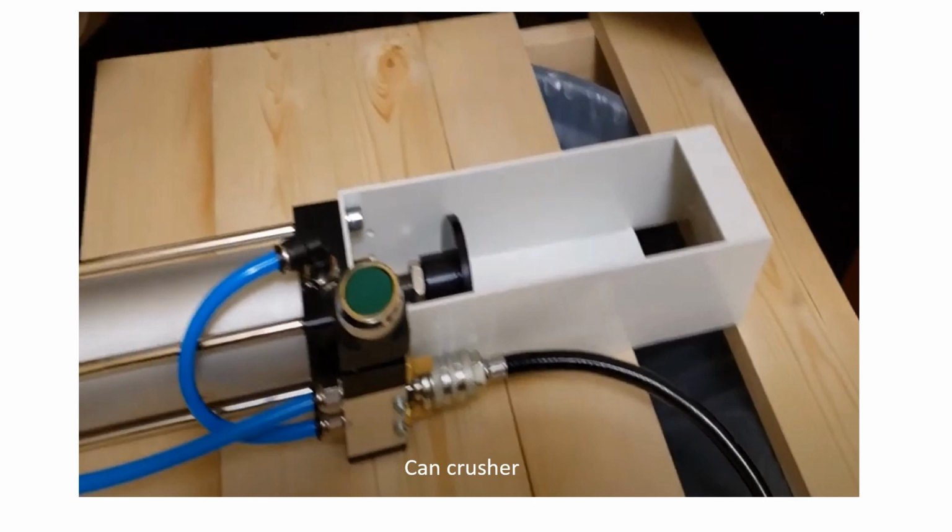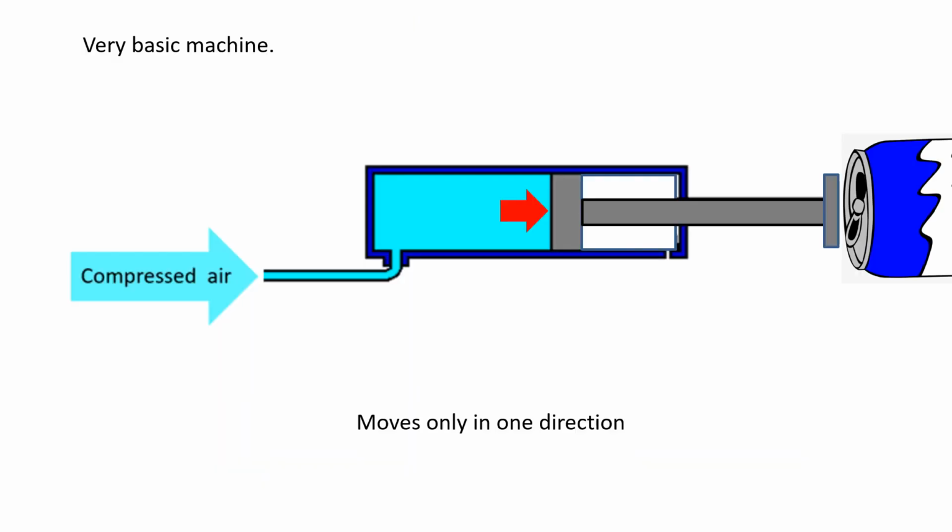Note the operation: as the operator removes his or her finger from the actuation button, the cylinder returns or retracts. Here we have an example of a very basic pneumatic circuit. We just apply compressed air to the extension port of the cylinder and the push rod extends. This is not very useful as there's no way to return the push rod back to the retract position.